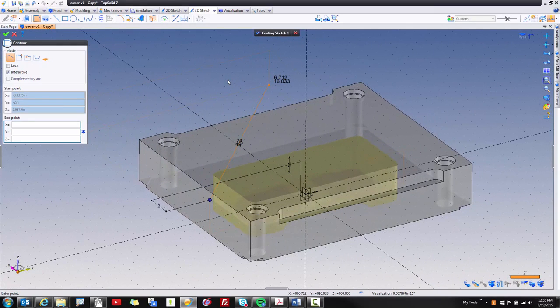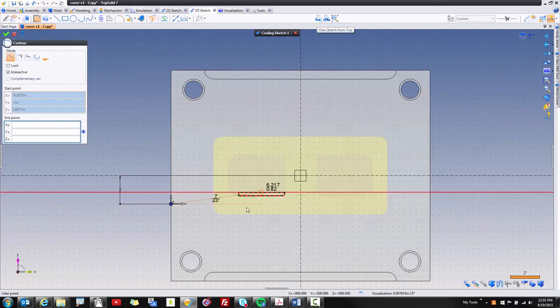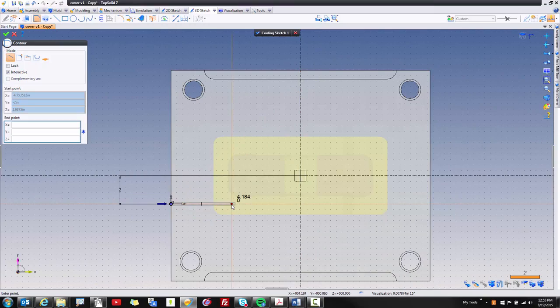What I'd like to do is switch into a local plane based on where I started this sketch. To do that, I'm going to use a keyboard command. Hold down the Control key plus the space bar, and you'll see a plane just showed up right here. If I keep holding the Control and keep tapping the space bar, it toggles through all 3 sets of standard planes. So maybe I'll start there, look straight at it, and come across to right here.